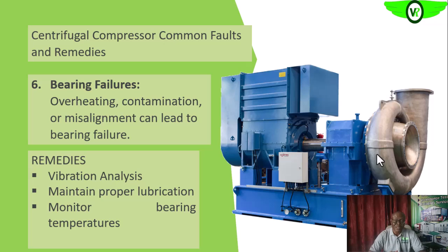It's even a simple means of looking at the health of the compressor, so that if it is increasing, we can bring in other technologies to help us ascertain what is actually happening within the bearing. Then once it is too excessive, we can inspect for damage.